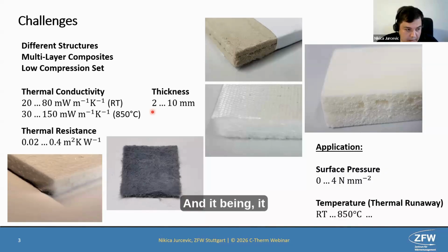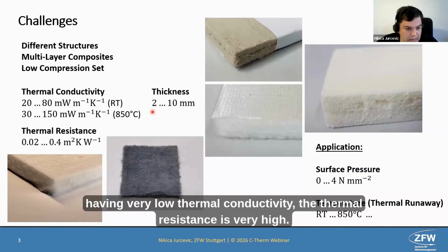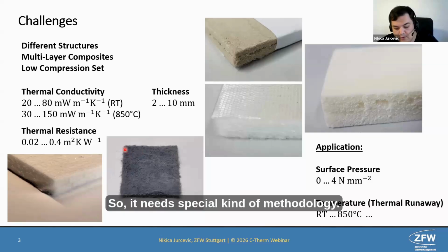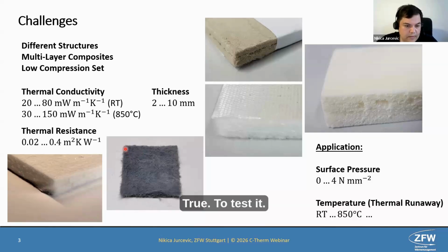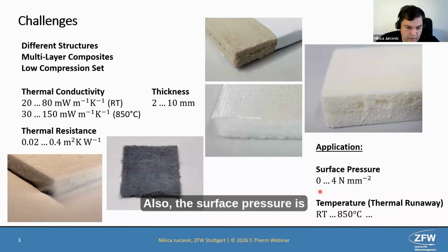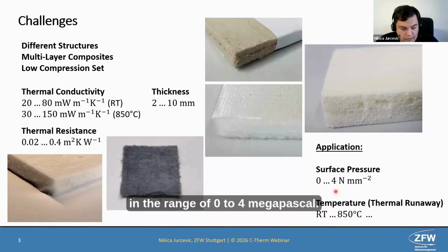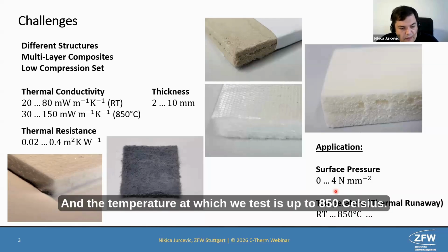And having very low thermal conductivity, the thermal resistance is very high. So it needs a special kind of methodology to test it. Also, the surface pressure is in the range of 0 to 4 megapascal, and the temperature at which we test is up to 850 Celsius.